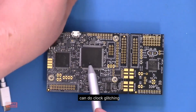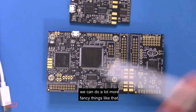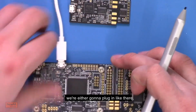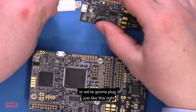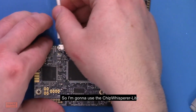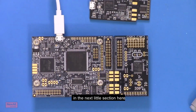The ChipWhisperer Lite, I should mention, can also do clock glitching, something that's not possible on the Nano. With the FPGA on the Lite, we can do a lot more fancy things like that. But the basic idea is exactly the same. When we go to use it, we're either going to plug in like there, or we're going to plug in just like this. Whichever you're using, all you've got to do is plug in to the device, and you're kind of good to go. I'm going to use the ChipWhisperer Lite, and you just need to remember that in the next little section here.